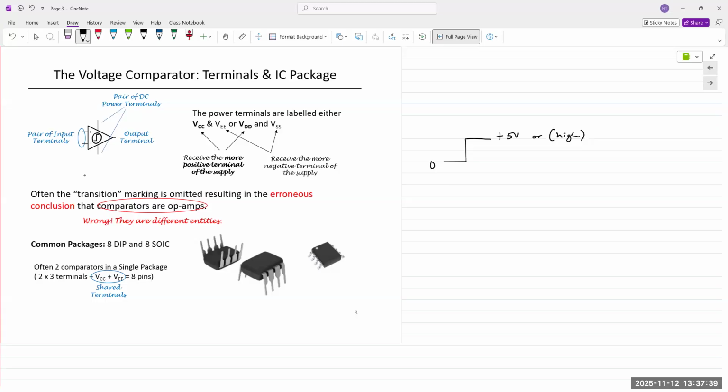Okay. So if it's an oven, you want to heat it to 350 degrees Fahrenheit. You set 350 on the front panel. That means internally on the digital circuit, you're setting one terminal of the comparator at 350. It heats up because the signal tells it to send power to the electrical coil. The coil heats up, and when the temperature reaches 350, the comparator sends a signal and shuts it off. Does that make sense?